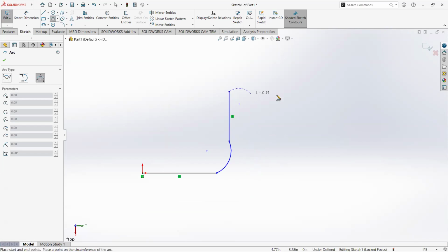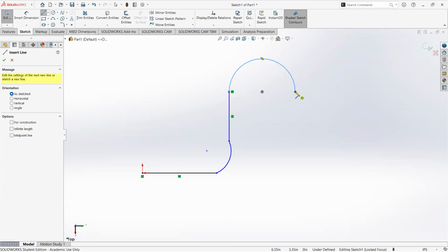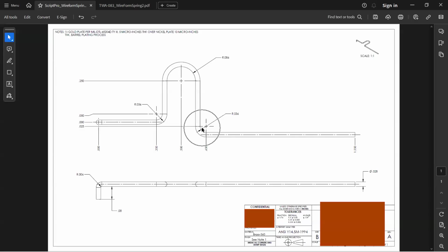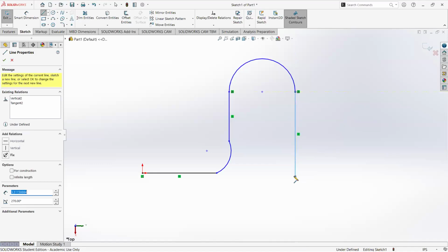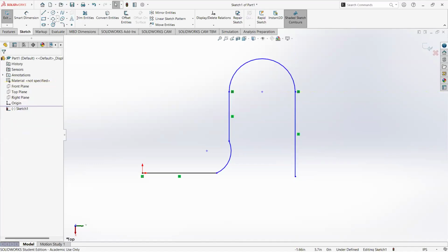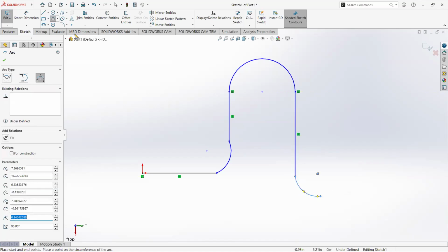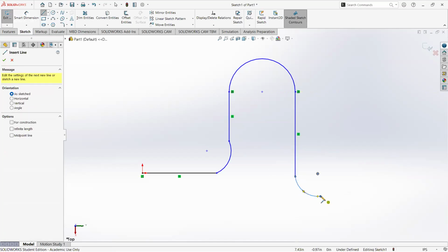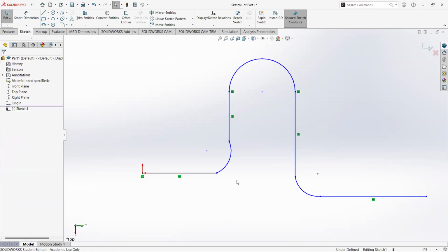We're just getting the general shape correct. Another 3-point arc. This one comes all the way across. I'm going to let this one go ahead and snap its tangent relation in there because that's fine. I'm going to want it anyway. Now, this other leg dips down below that line, so we might as well draw it that way to begin with. We'll come down, we'll drop down below that original. We need another arc somewhere over this way, and a line to finish us off. We'll make sure we get horizontal. We'll let the automatic horizontal constraint snap in.